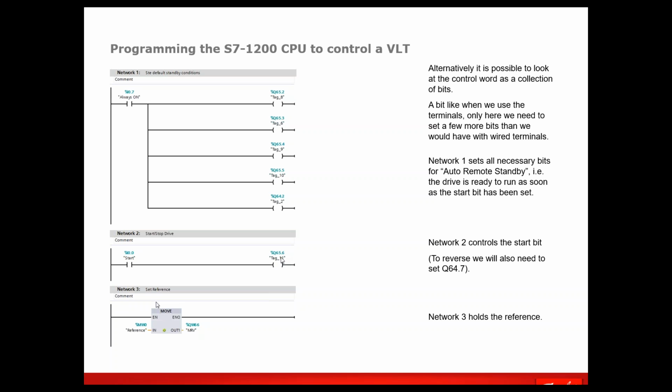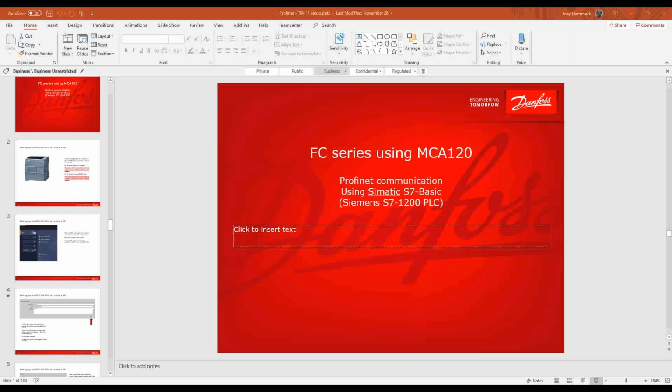It's the second word though, that's why it's a different one, but yep, bit 6 to start/stop. So instead of moving the whole word, we're just changing the bits, and the same way, just moving the reference. That is it for this presentation.